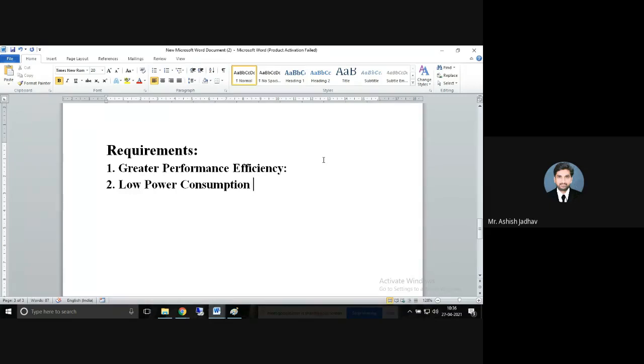So, in order to ensure low power consumption, your Cortex M3 has a lot of things. For example, it has two different sleep modes, two different instructions to enter a sleep mode. Then it has WIC, it has the sleep on exit feature, right? All those things ensure low power consumption. So it will enable longer battery life, especially critical in a portable product, including wireless networking applications.